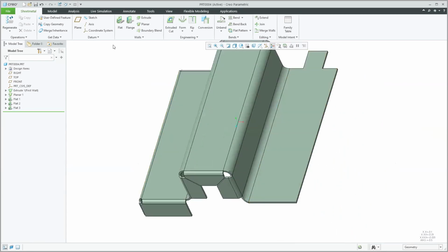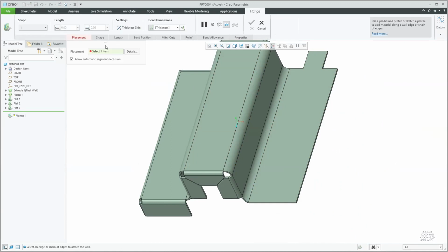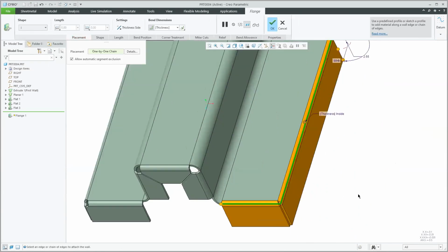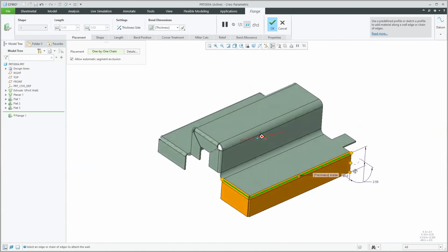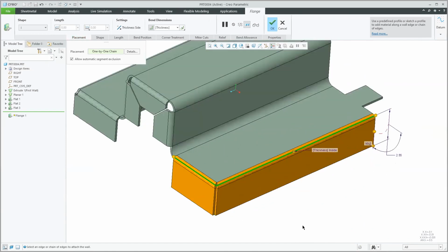Now let's do a flange wall. Now with the flange wall, again, you can hit the button. Again, you've got the different shapes over here, so very similar. And I'm just going to start with the eye wall. And if I just pick this edge right here, and don't do control now, do shift, you can pick the next edge that you want to add. And then it's going to add on to that. Again, I can't pick an unconnected edge. That won't work on there. And that's going to start to create the wall.